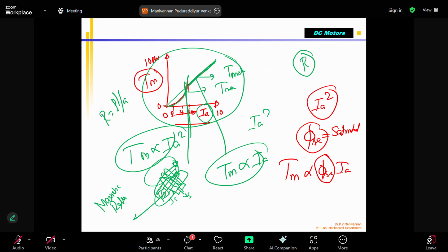If the core is a magnetic material, the flux enters inside it. From the coil it is generated, and it enters the core here. So this has magnetic reluctance R. That's the magnetic reluctance equation. Last semester, when we talked about mechatronics and the inductor, I talked about this. There is a formula involving the cross-section area of the core and the core material properties, similar to resistivity. All these things form the reluctance. This decides how much magnetic flux can go. Beyond a certain point the flux cannot enter, because it depends on the material property and the size of the cross-section area.